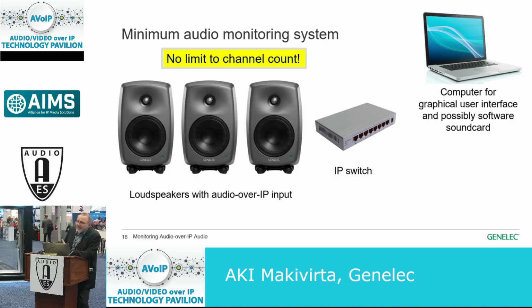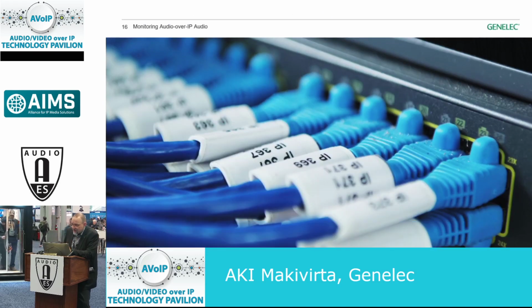The important point to make here is that there are no usual limitations that you would assume to have in an audio environment. So for example, you don't have any absolute limitation to the number of channels that you'd be able to reproduce. All you have to do is bring in more loudspeakers, get them connected, and you're in business. And the PTP clock synchronization will take care of synchronizing all these different devices so that you can create a coherent, properly working audio image. I'll come back to that in a moment.